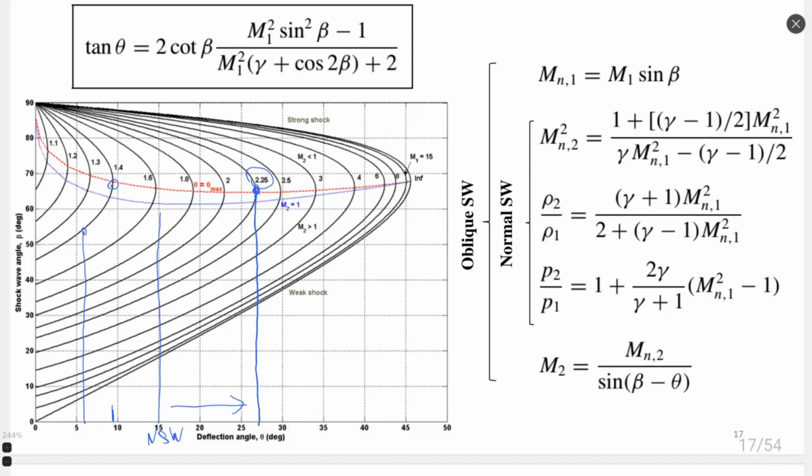question of model, we see here on this screen a complete set of equations you need to calculate one oblique shock wave or a series of oblique shock waves. So the theta-beta-M equation: the relation between flow inclination, oblique shock wave angle, and Mach number before this shock wave.